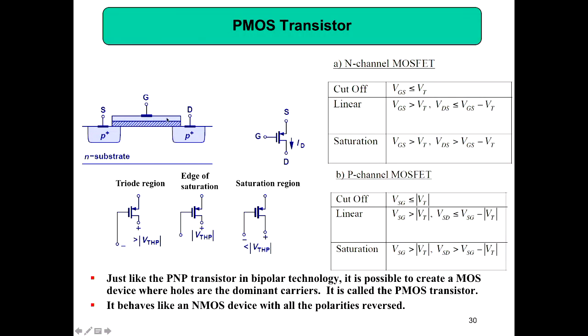But then when you increase this negative charge, holes will come out from here and mainly here, and also some from here, where there is a minority but not much. Mainly they come from these two regions, and then you get a channel made of holes in the N substrate. So that is the PMOS operating normally. Then suppose you connect a positive charge here for the PMOS, what will happen? You get positive charge, positive charge, positive charge, and this will attract the electrons here. So will it operate or not?